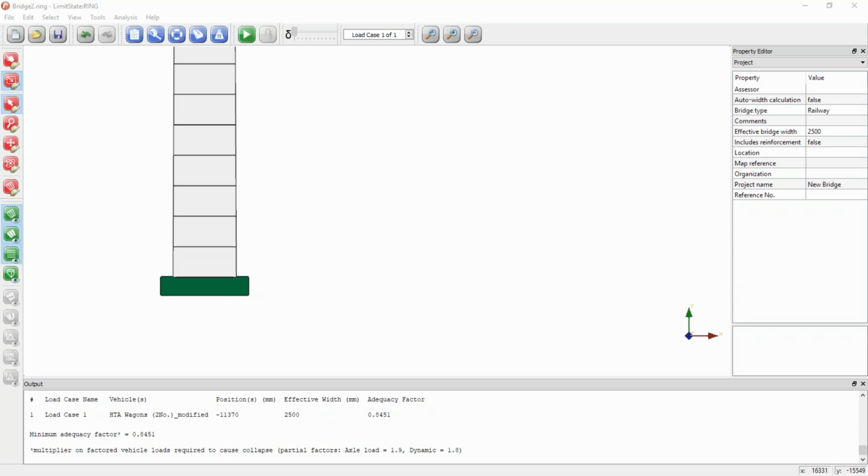There's a question here. Where you have longitudinal fractures, you mentioned effective width should be limited because you no longer have transverse distribution in the barrel, but the load will still be carried by the portion outside the fractures. Therefore, isn't it overly conservative to limit the effective width? So I think you will have some distribution, arguably, through the fill onto that adjacent section of masonry, but you will have much less distribution than is indicated, for example, in typical assessment codes. So I guess it comes down to engineering judgment as to how conservative you want to be.